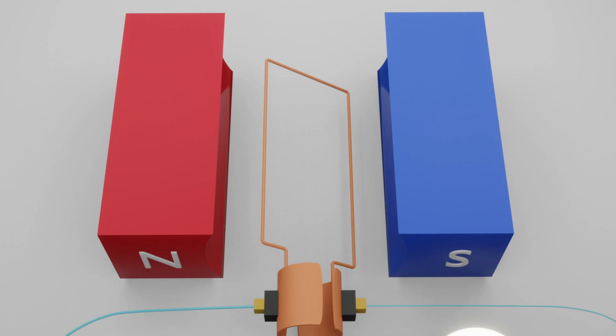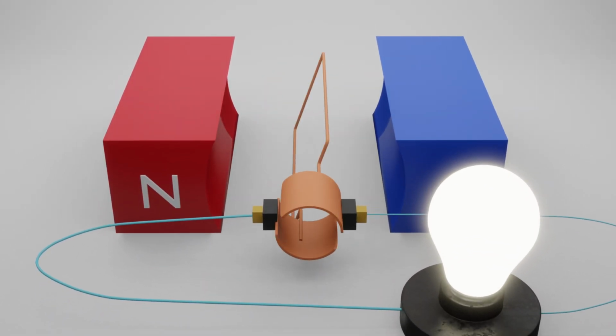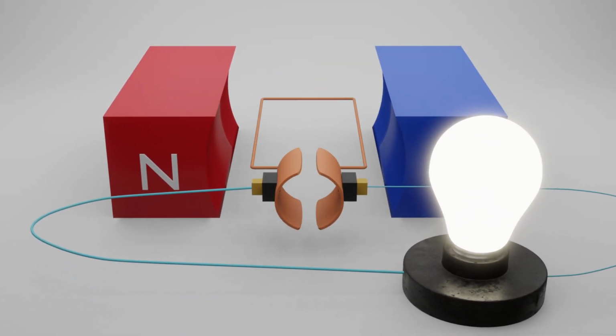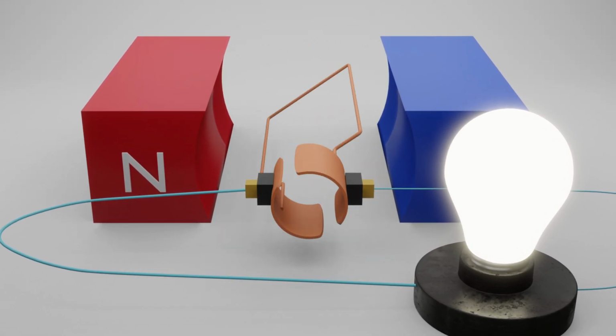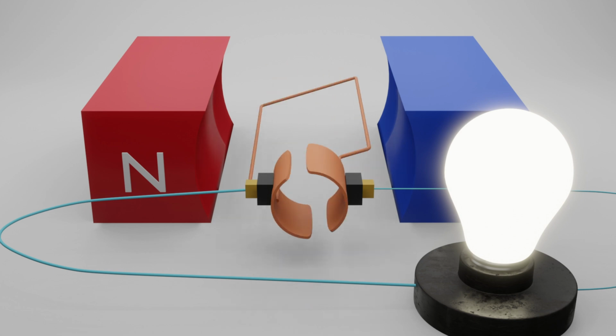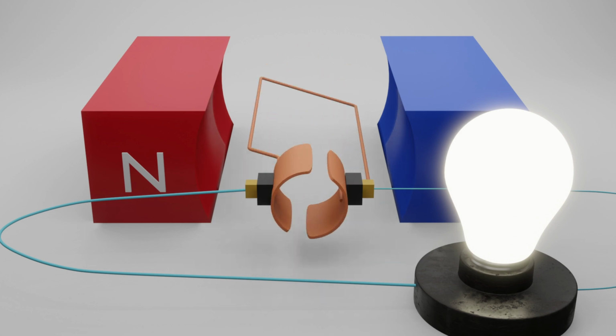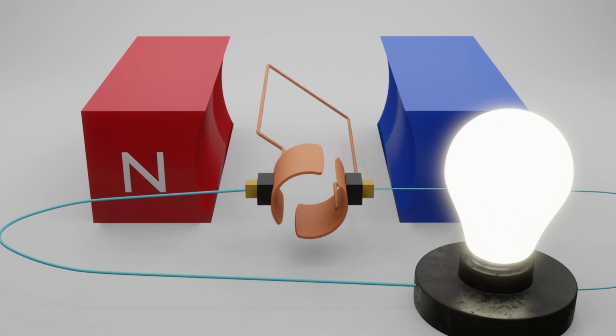Critical speed is defined as the speed at which the shunt field resistance of the generator matches the critical resistance. It is the speed below which the shunt generator just fails to build up its voltage without any external resistance in the field circuit. But what does that mean in practical terms?